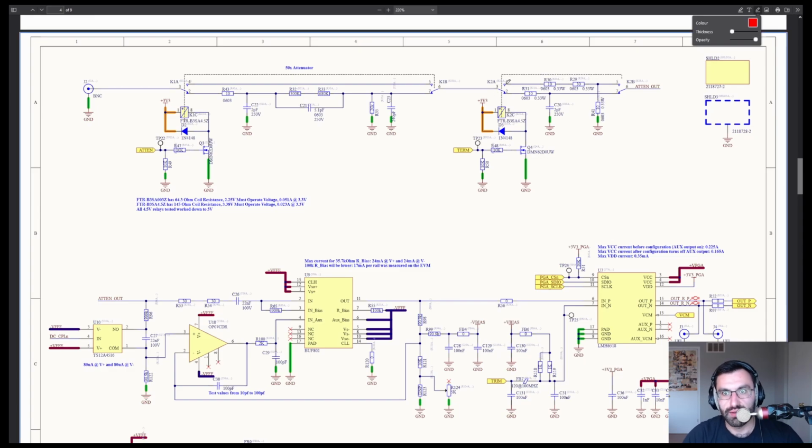And as we discussed in the gain attenuation video, we actually have the termination in the form of a divider. It totals to 50 ohm, and it's a 5-to-1 divider. Now, why do it this way and not just put a switch way out here with a 50 ohm resistor? Well, if you put it up here, you can just use the normal 1 mega ohm attenuator, and you don't have to worry about different voltage ranges and all of that.